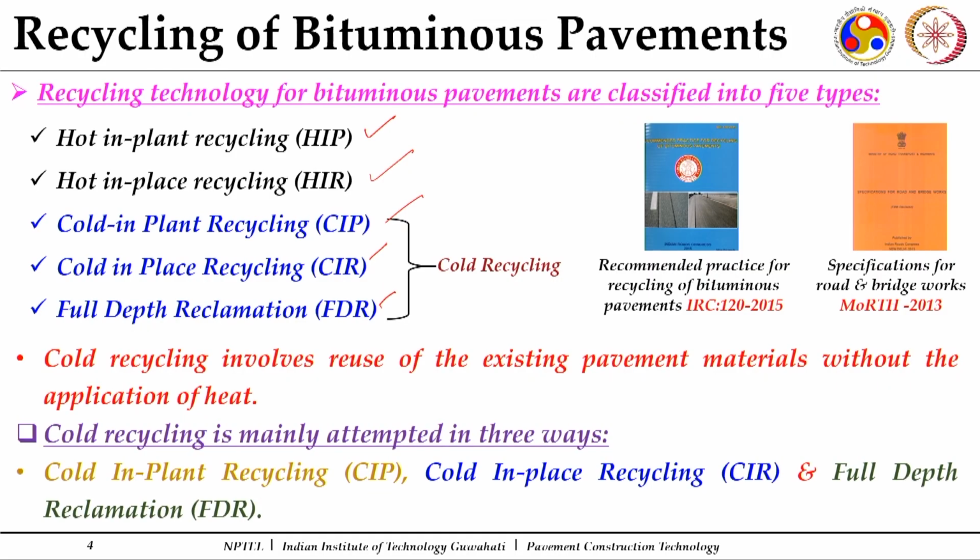So, as the word itself says, cold means there is no heating involved. Cold recycling involves the reuse of existing pavement materials without the application of heat. As in the case of hot mix recycling, when we talk about cold in plant, the recycled mix is produced at a plant. When it is in the field or in situ, it is cold in place recycling. There is a small difference with full depth reclamation.